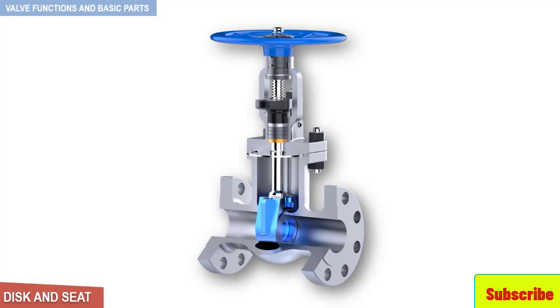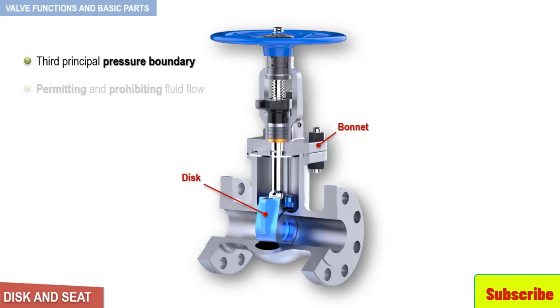For a valve having a bonnet, the disc is the third primary principal pressure boundary. The disc provides the capability for permitting and prohibiting the flow of fluid. When the disc is closed, full system pressure is applied across the disc if the outlet side is depressurized. For this reason, the disc is a pressure-retaining part.